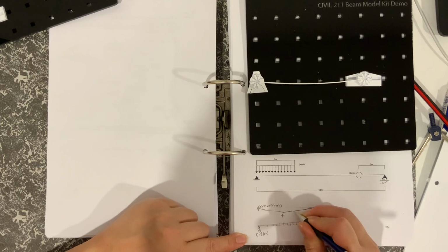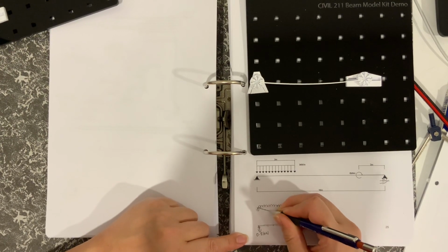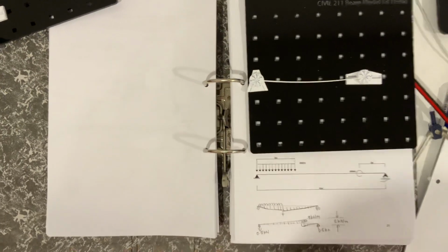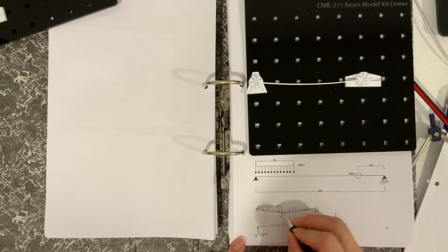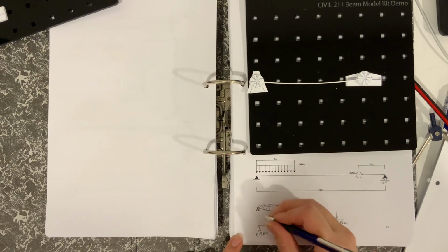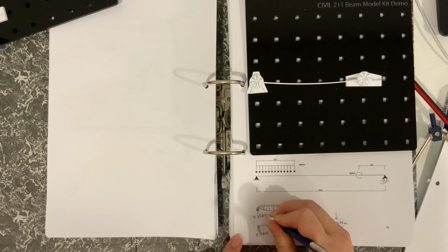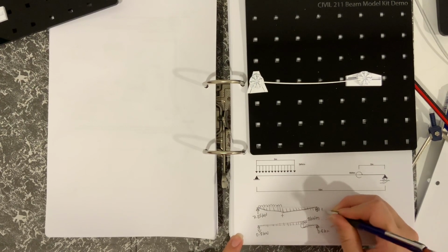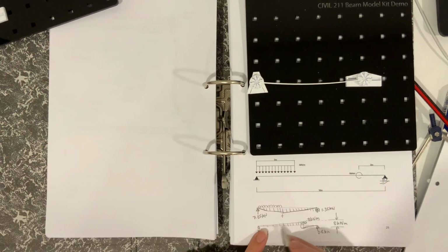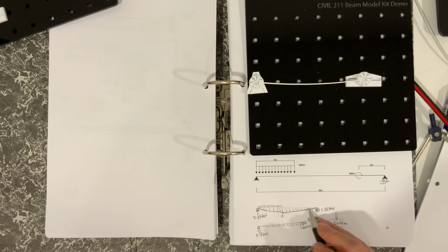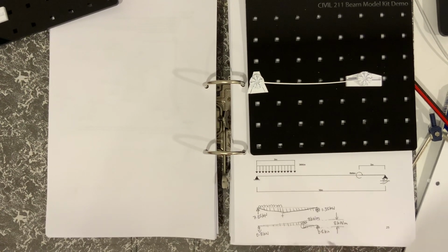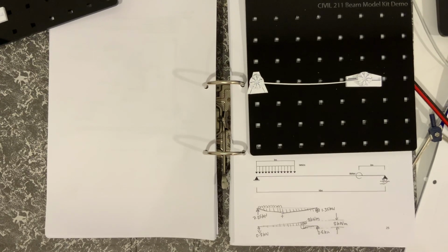So that would be a straight line, and that would be a line with some curvature. And under that, the 3 kilonewton meters, you would probably find that reaction is 7.65 kilonewtons, and you would probably find that reaction there is 1.35 kilonewtons. And the point is that you would then be able to add the two bending moment diagrams together to give you the final solution.